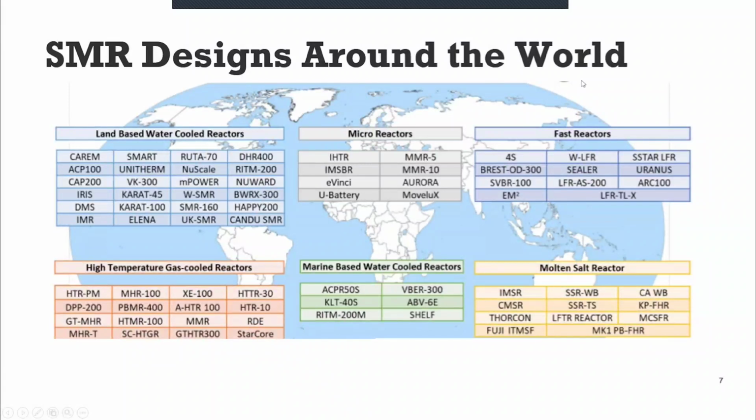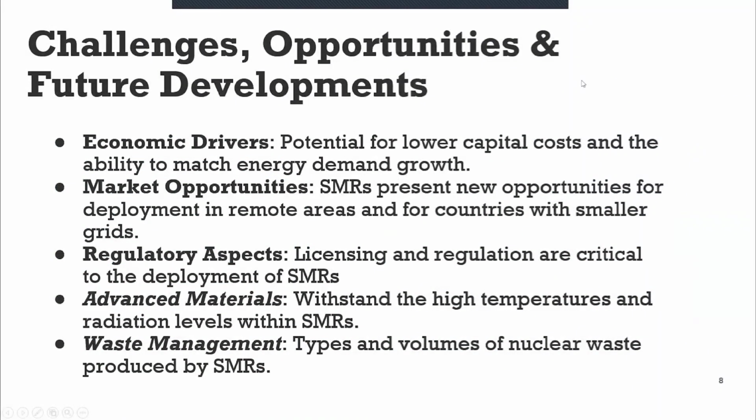So now let's go next, whereby we will be looking at the challenges and opportunities around small modular reactors. Starting with the opportunities, there are economic drivers. Why are we saying so? Because they have the potential for lower capital costs and the ability to match energy demand growth. As energy demand changes, maybe we have a small modular reactor producing 300 megawatts electric, and in a year our demand has increased to 400 megawatts electric. With small modular reactors, we can add other modules to match that demand.